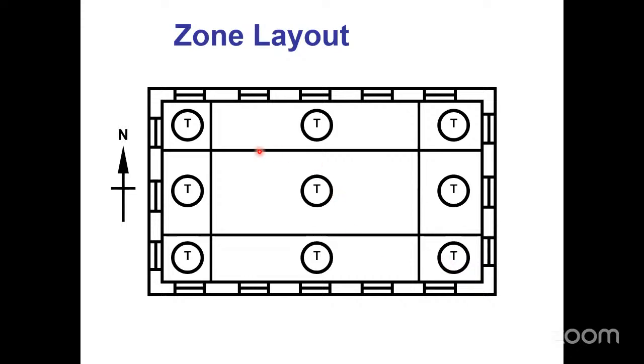Maybe this is a really, really big zone in the middle, right? And maybe the left half side is accounting and the right half side is IT support. And the IT people are there till 10 p.m., but the accounting people go home at 5. You may want to have different zones because the schedules are different, right? Or maybe this zone over here, maybe it's actually 3 offices and then a conference room. Well, grouping the 3 offices together is okay. I mean, everyone wants their own thermostat, but everyone's not important enough to get their own thermostat.